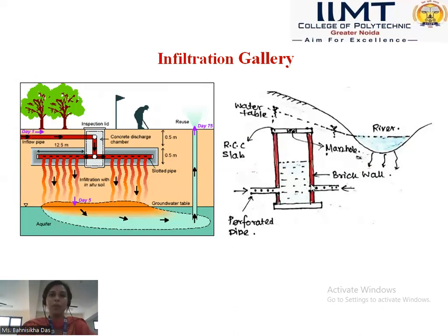Into this chamber. So there is a series of chambers constructed along the bank of the river, and those chambers are connected through these perforated pipes. All the water that is available in this particular geological formation will enter into this chamber through these perforated pipes.